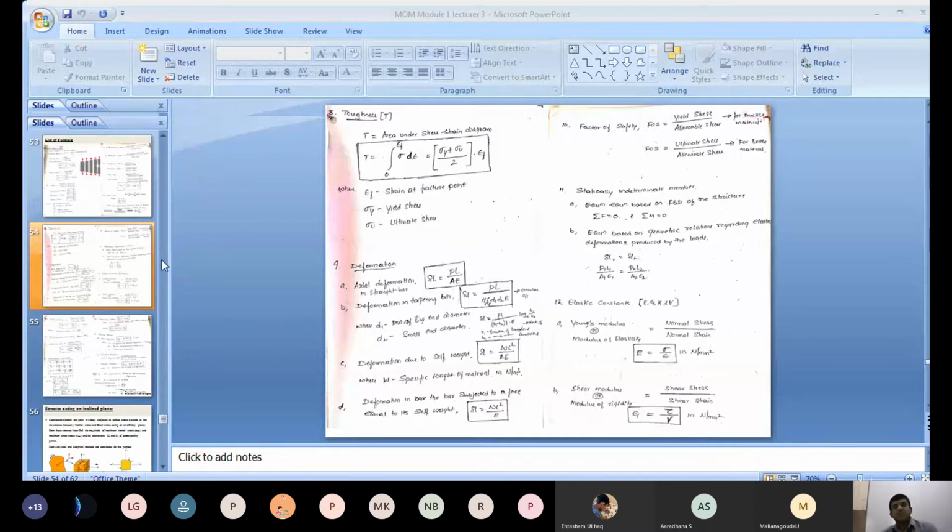Next, very important formulas now. One is, you consider a bar, a mechanical member or aerostructural member, you consider as a bar. A bar is nothing but a member you subject to what type of load? Only axial loads. It may be tensile or compressive in nature. Now consider a bar. If it is a straight bar with uniform cross section, what is the deformation?